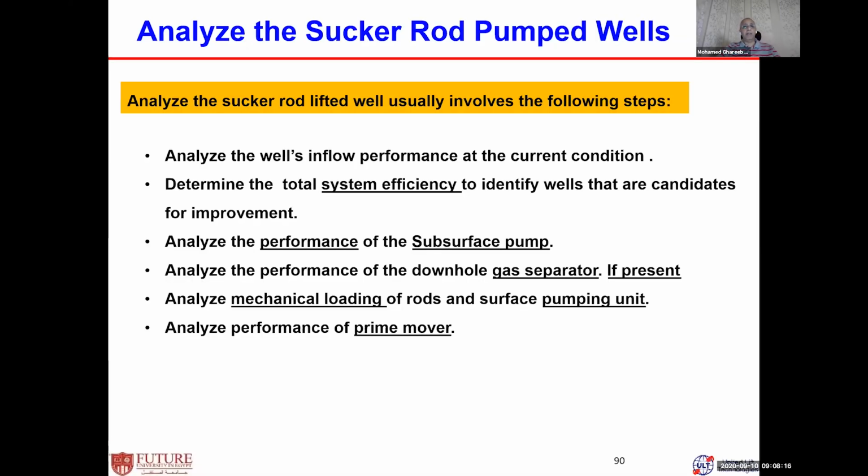Analyzing sucker rod pumped wells, or reciprocating pumping wells, beam pumping wells. I try to give you four names in order to be familiar with all of them. If you notice, I changed it, but at the end, it's the reciprocating sucker rod pumping system. Analyzing the sucker rod lift and pumping system usually starts from your well inflow performance.